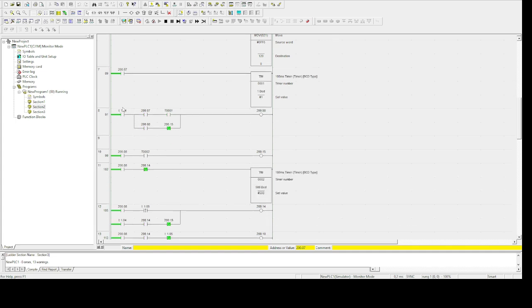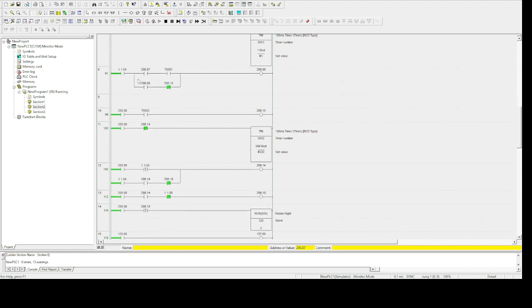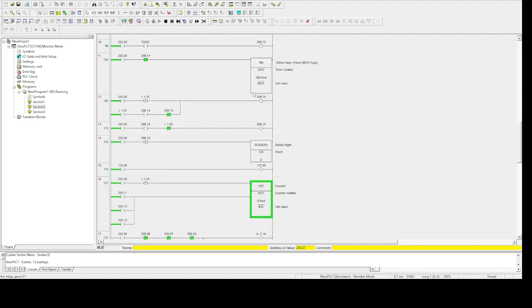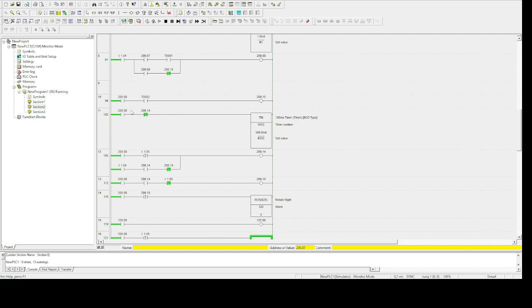So here we're going to set the microcontroller output into the input of the PLC, so this bit or input will say that the microcontroller expects at this point that the PLC will send the 16 bits, or 16 pulses. And this bit is made, and this is the bit for the loop. The loop is made with a timer; in case nothing happens, the timer will reset everything again.